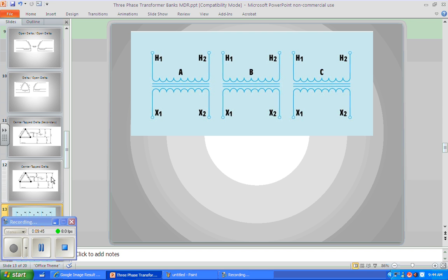We're going to go delta Y delta where we have a delta load. And just to keep things interesting, we're going to do a center tap delta where we can get some different voltages. And we're going to imbalance the loads. We're going to load one transformer more than the others. We're going to have a single phase load on those also. So won't that be fun? So it'll be a delta, open delta, and then either a delta load or a Y load, your choice. But that's another project that you can do.